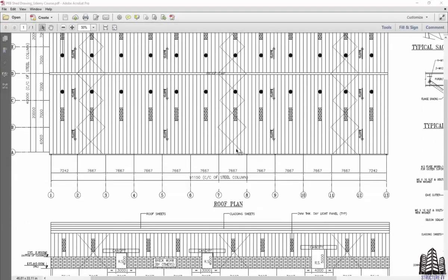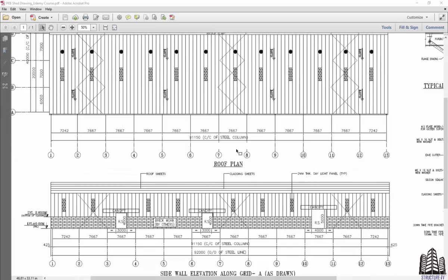In this lecture, we will learn how to draw the plan and elevation bracings. Bracings are a very essential part of a steel structure. Without bracings, steel structures are somewhat not desirable, although they can be stabilized by taking box sections and strong hollow sections to avoid torsional buckling. But bracings are always desirable so that wind and seismic forces can travel via compressive forces and tensile forces.